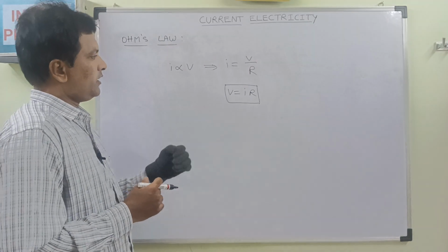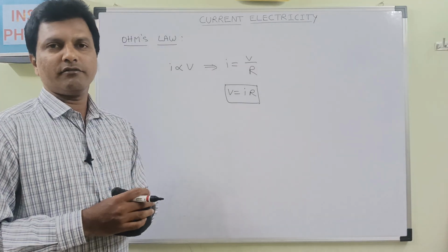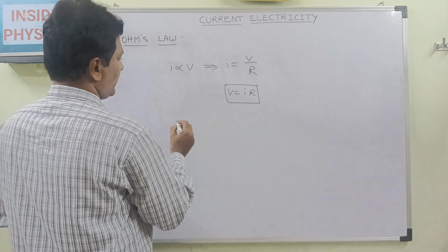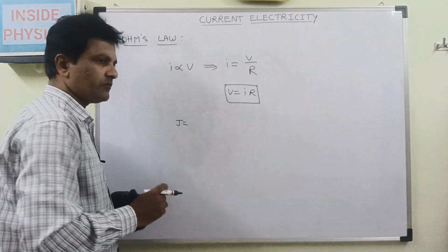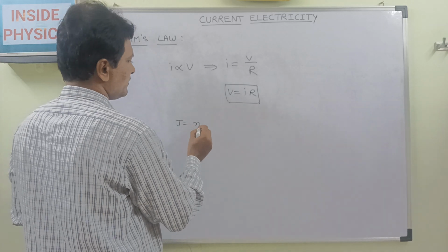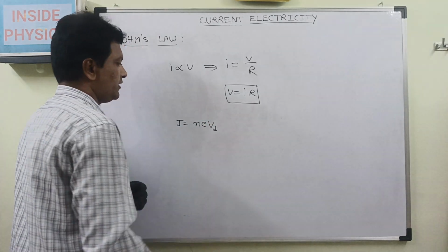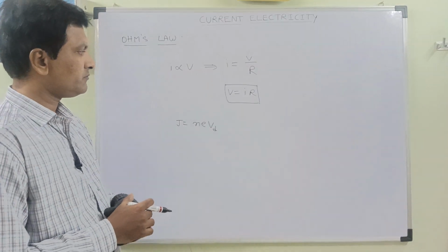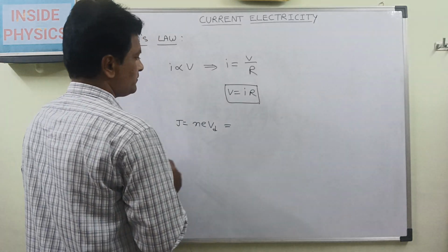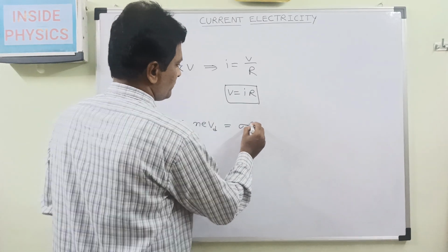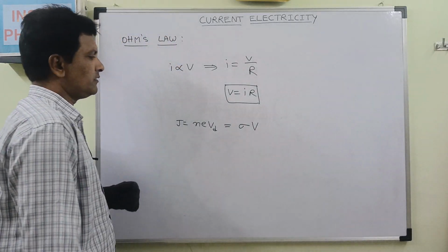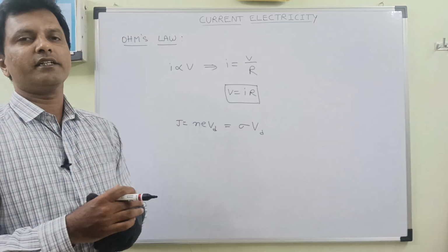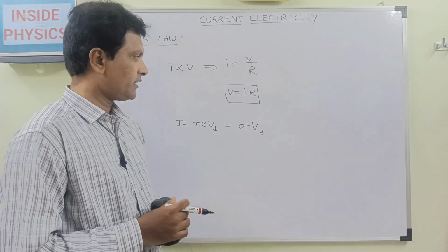So if you observe Ohm's law in a microscopic way, a little more closely, we can write it in another form like J equals n e vd, drift velocity times electron charge times the number of charge carriers. Okay. So we can write it in the form of J equals sigma E, where sigma is the electrical conductivity of the material or conductor.